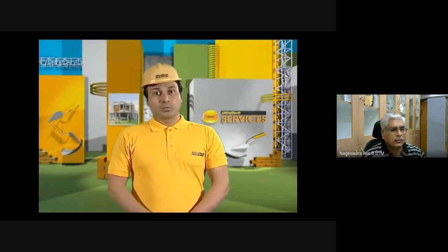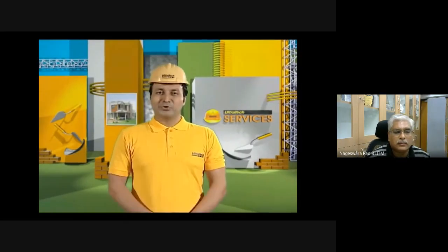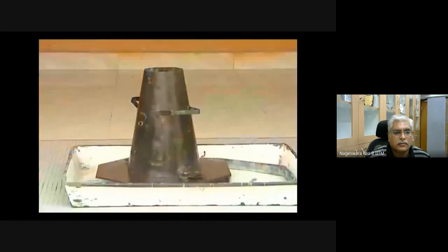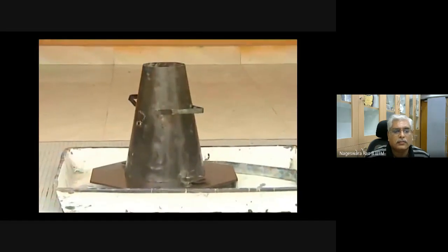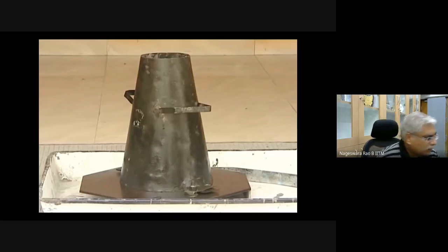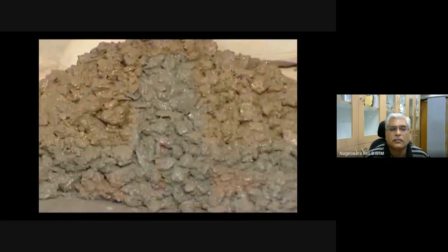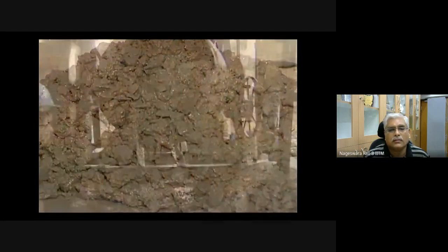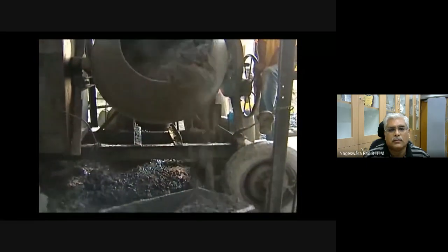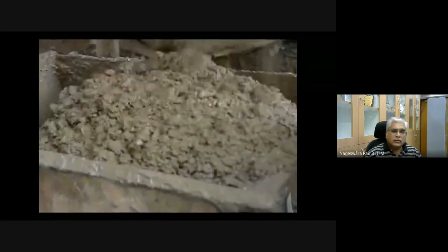The ease with which one can work with concrete is called workability. This can be measured using a simple test called the Slump Test. Let me show you the procedure. Slump cone test is a simple and popular test extensively used at sites to assess the workability of the concrete mix. The test should be conducted at the commencement of the concreting operations or whenever the workability of the concrete changes.